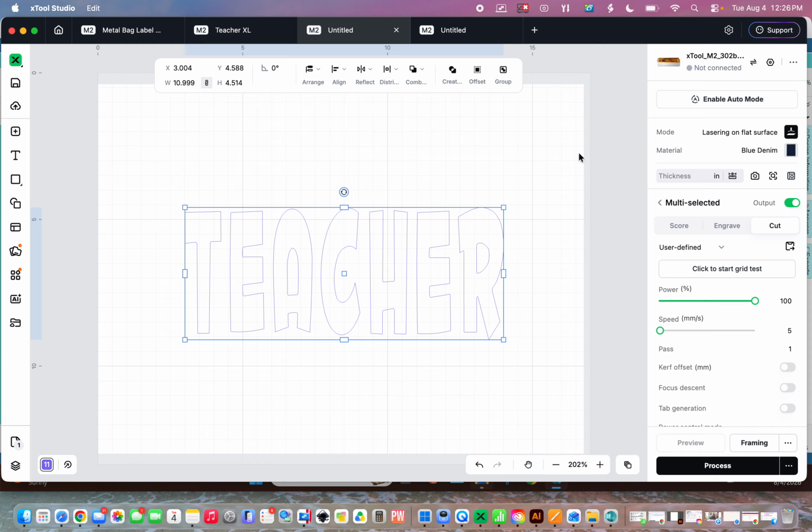And oh, another thing I wanted to add really quick is the laser especially is really good if you're using a fabric that tends to fray, because that laser is kind of sealing it in as it cuts, so you're not going to have to worry about it fraying.